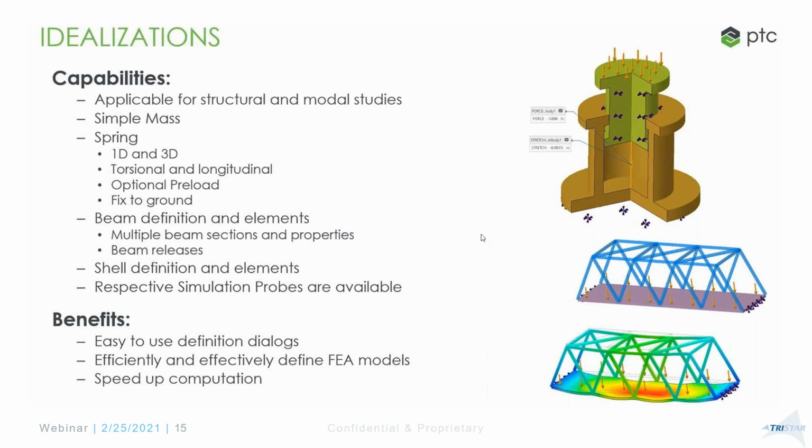And then I could analyze the geometry that I may be interested in. So these are all idealizations that will be very helpful if you have sheet metal parts or thin geometries, wherein shell idealization becomes important. Right now it's surface shells mainly that are supported, but in the future, mid-surface shell compression may also be supported, in a future release.